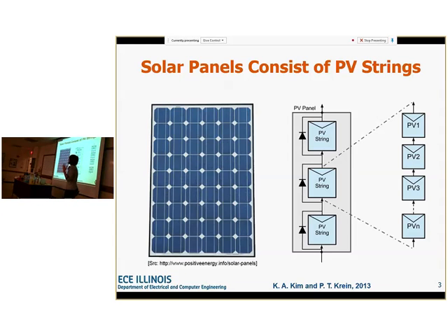So first of all, let's go back to the actual PV panel. This is a pretty typical panel. When I look at this, I see 3 strings. You may not see that right away, but the way it works is each cell is about 0.5 volts, and in order to reach the voltages we need to connect to the utility, we usually put them in series. So all of these are strung in one string, and there are actually 3 strings here. It goes from the top usually back down, and usually there's a little junction box behind here. That's why they string it up and around, so you have the 2 ends of the string and you connect them in the junction box.